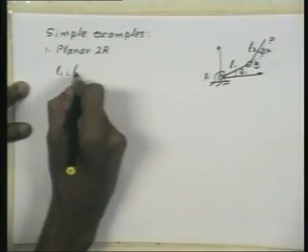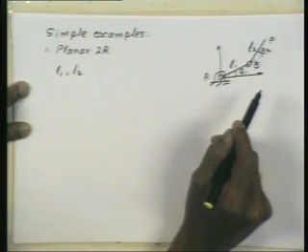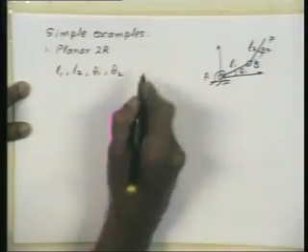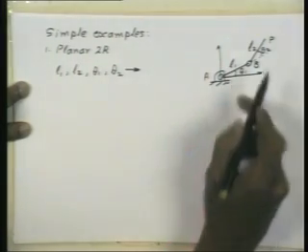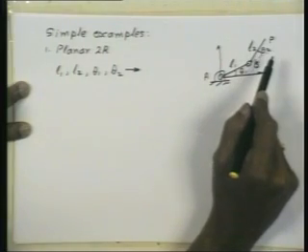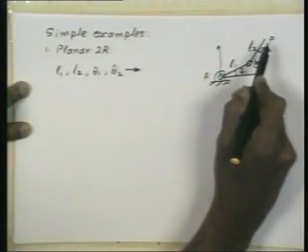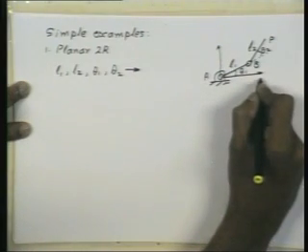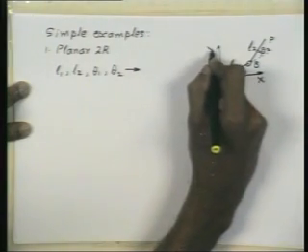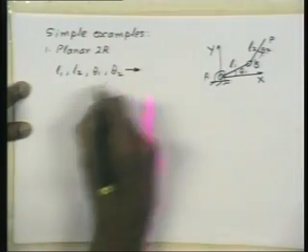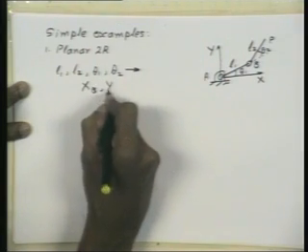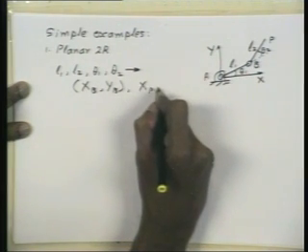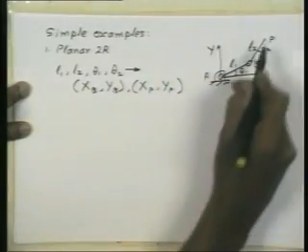So what are given are the link lengths, right? And the joint angles theta 1 and theta 2. You need to determine the position of the two links, right? So maybe if you determine the position of B and the point P, you know where the links are, right? So let's call this the global reference frame. In this global reference frame, the coordinates xb, yb, that is the position of B, and the coordinates xp, yp, position of P.